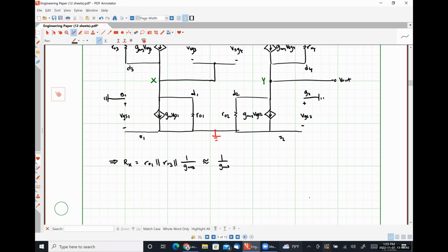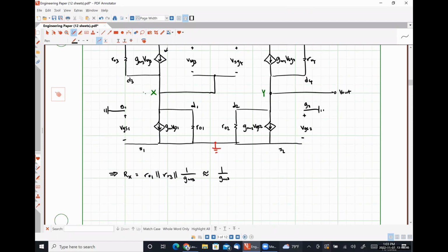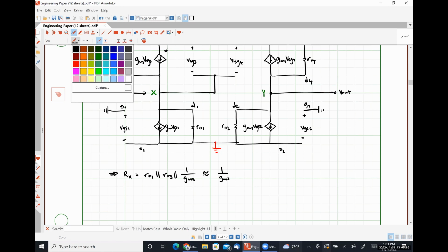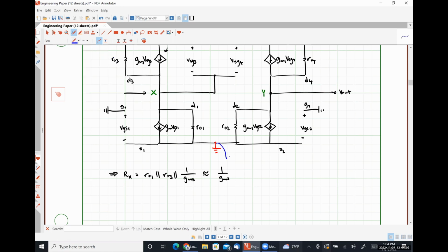If we put a test source between here and ground, it would more so look like R01 is a dangling thing. Now, in truth, what we would actually see would be the internal resistance of our tail current source being degenerated by there. And that's just going to make the math harder. It's also going to make R01 look even larger because that's what degeneration does, which is not going to change the results of our analysis.